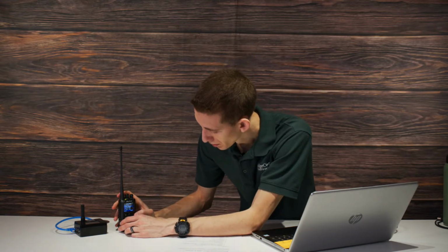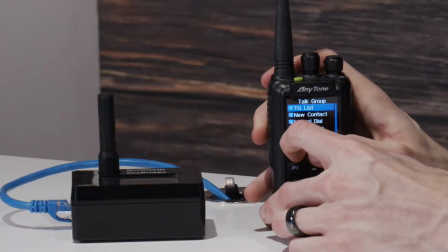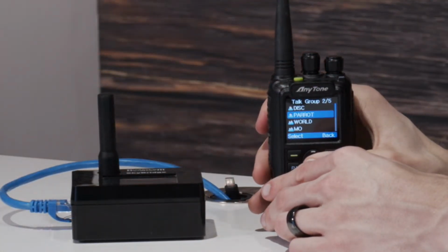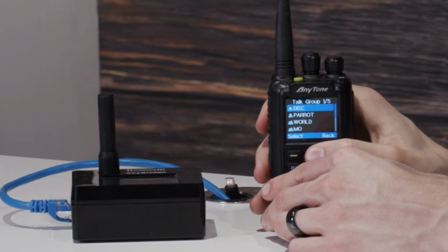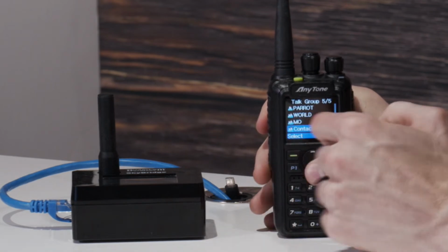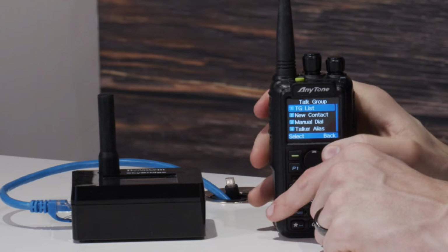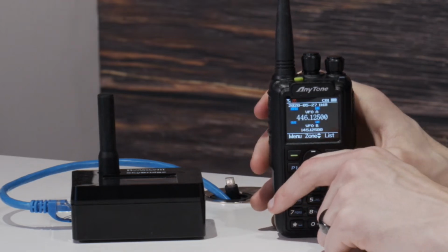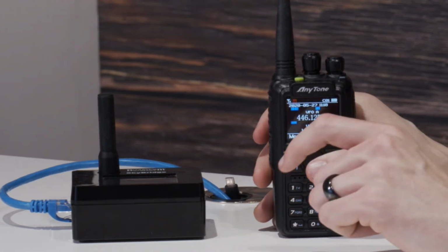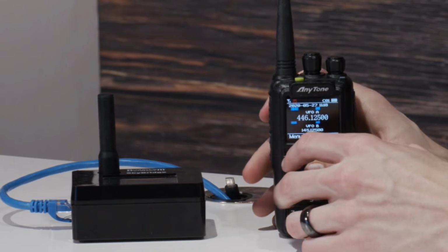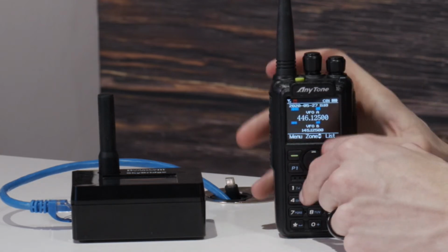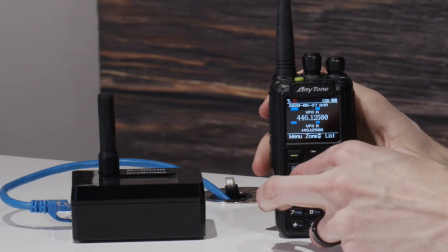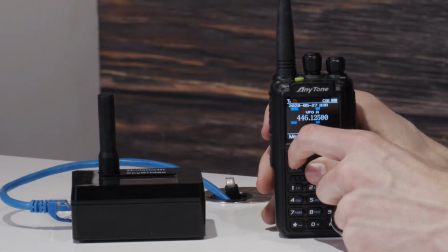So we have our talk groups. Now we actually need to go create our channels. After that, we'll assign our talk groups to those channels. So if we click on our talk group list, we now have the Parrot, the Missouri, Worldwide, and Disconnect all in there. And then that original one, which we won't be using. Awesome, so at this point, we're good to go there. So now we can create our first channel. Now I'm just going to use zone 1, which comes in the radio. You could also create more zones, but in this case, we're going to add our channel.